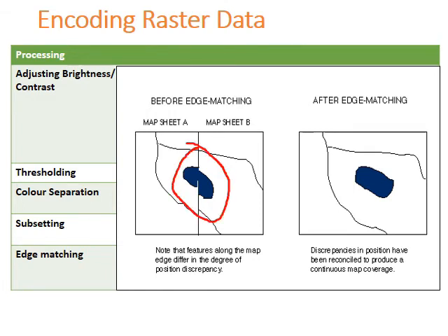But when you do a process called edge matching, the two different maps will be combined into one map, and all those edges are matched properly, and this process is called edge matching. This is very, very important when you use two different maps or many different parts of the map, and you want to bring that into one map, and you use a process called edge matching to bring this into the GIS environment.